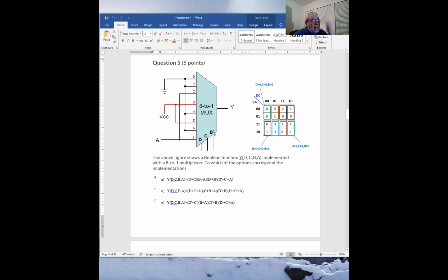So this would be the most representative variable, this is the second one and third one, and this is the last one. From the most significant here, D, to the least significant, that is A. So the idea is that in order to maintain the same order of the minterms, we are supposed to do the reverse, or the change, in the variables in the K-map.